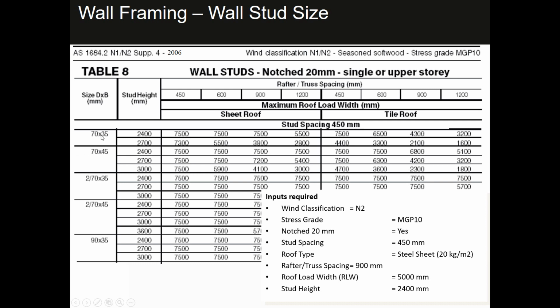Well, these are our sizes down here. Do you go through the example? So we've got our wind classification N2, our stress grade MGP10, stud spacing at 450 millimetres.